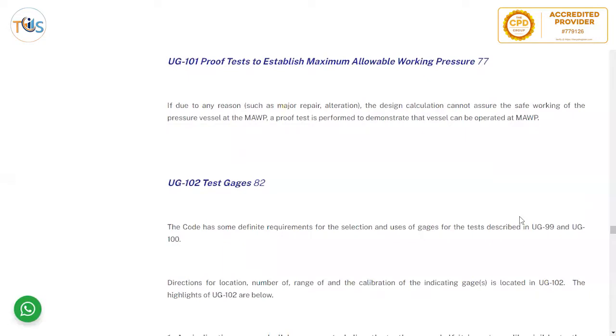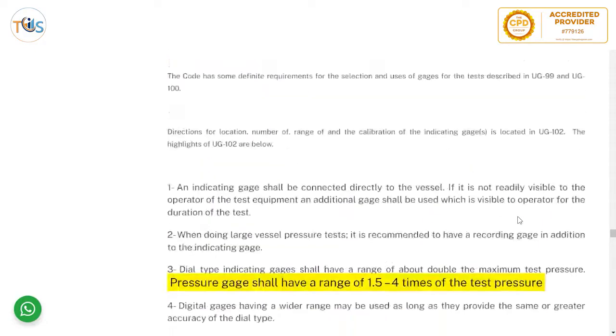This is just, how to put it, when you're not too sure, then you just pressurize it as a proof load. So if it can be to standard, then that means once a pressure test is done, we can always demonstrate that it's safe to take the pressure to maximum allowable working pressure. Practically, that's what it says.